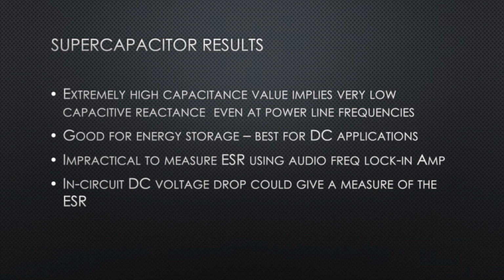They're good for energy storage applications where you're drawing a large amount of current. So if you want to measure the effective resistance of these caps, you could probably just load them using a large current and then measure the internal voltage drop that is seen at the load, and that would be a practical way of actually evaluating supercaps, I feel.